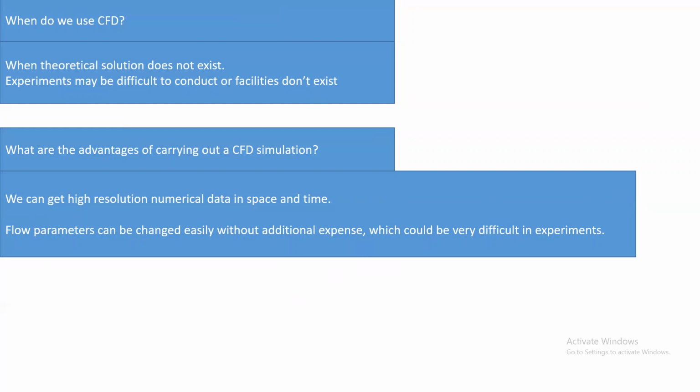What are the advantages of carrying out CFD simulation? There I have written, we can get high resolution numerical data in space and time. I am giving you an example of the IC engine. Within the IC engine, at whichever point you want to calculate the velocity, pressure, or temperature, you can calculate. If you are doing the CFD simulation, you can select a point, and it will show you the velocity at that point.